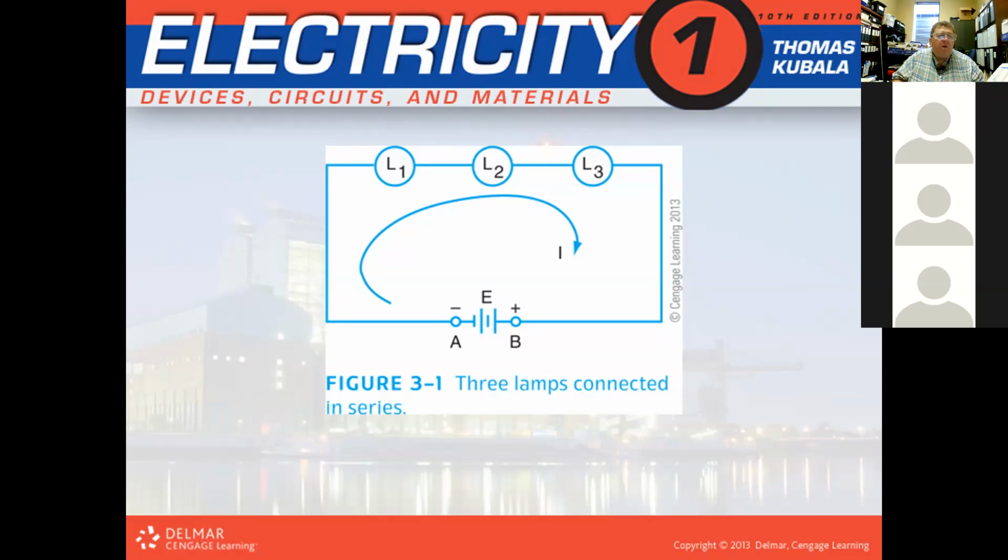4. Exactly. So if you put a voltmeter across lamp 1, it's going to read 4 volts or very close to it. There'll be some tolerance because the resistance of the bulbs is not going to be identical, but you can see it's going to be pretty close. And then if you read voltage across the second bulb, what would it be?